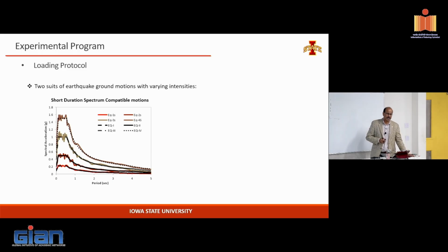So if you're doing analysis in a computer model, you should go through these motions, 2 sets of motions. We have published an article saying why this is important and what the benefits are, so that you're exercising both sides to make sure these structures can survive. In a lifetime, not a single structure is going to go through all of these motions, but these are damage-free, they are not supposed to experience significant damage, so we felt comfortable running as many earthquakes as possible.